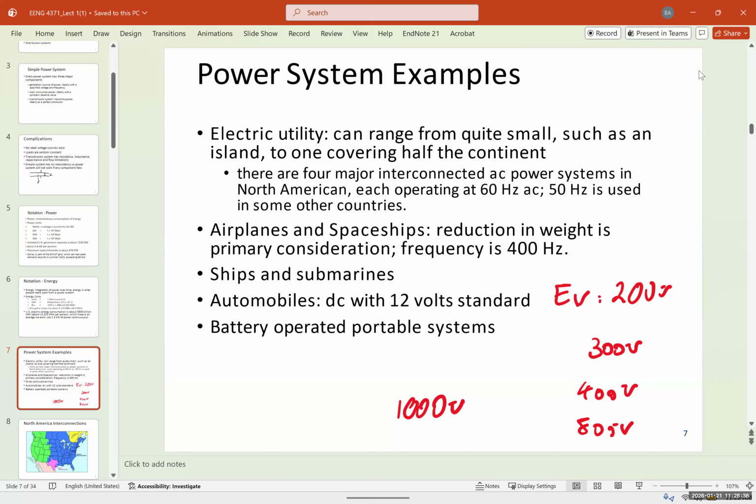The higher the voltage gets, the easier the power electronics side is, but you need much more insulation. A 12 volt battery is not dangerous at all. You can touch it and easily hold it. But anything above 60, 70 volts DC is going to be extremely dangerous. By the way, DC voltage, contrary to public belief, is way more dangerous than AC.